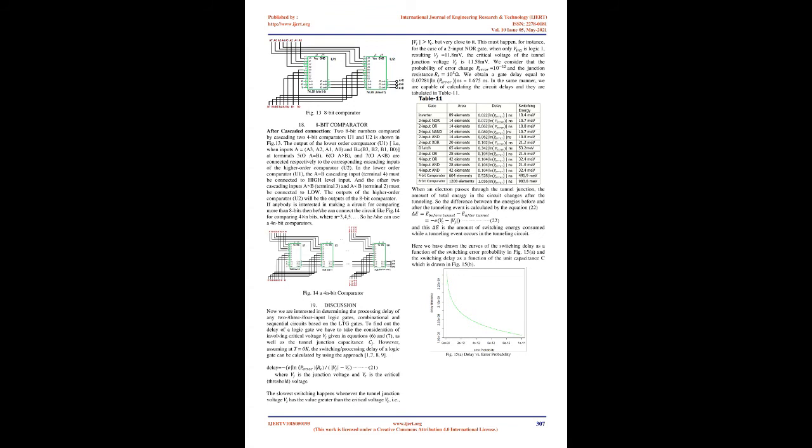As the comparator output condition levels are violated for the cases indicated by the red color box in table 9, all the cascading inputs in the red color box will not be taken into consideration. So the modified table to be accepted when 2 or more 4-bit comparators are in cascaded connection is given in table 10.